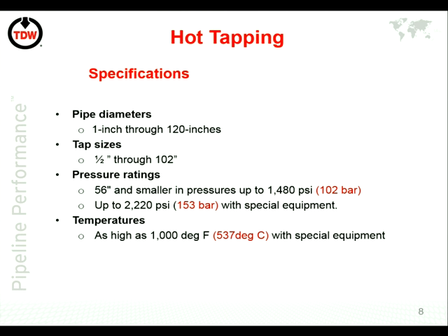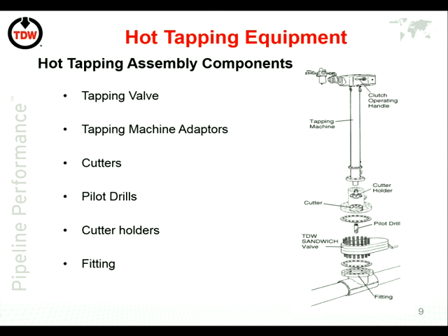So what is a hot tapping machine, or what is hot tapping equipment? And effectively it is a drill. So what you have is the drill itself, or the drill machine, the tapping machine here. The reason it's long is because the drill has to often travel quite a distance to get into the pipe, and it has to go through 1/2 of the pipe.